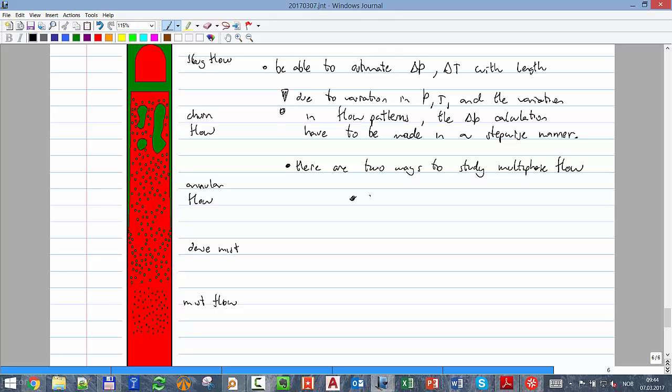One way is the steady state, and that's what we use for everything. For all of our calculations, we say we want to avoid transients. We say that this term in all the equations is equal to 0: the partial derivative with respect to time is 0. Why? Because we say we progress from one steady state to another in the life of the field, so there is no need for that.